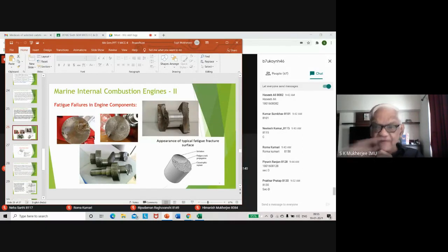That is called the fillet radii. I told you how much should be the fillet radii, 0.05 D. If you remember, when I was teaching you about the crankshaft, the radius of the curve at the point where the crank pin meets the web has to have a curvature, and that curvature is called fillet radii, because the radius is in all parts, all around, on both sides. So the plural of radius is radii.